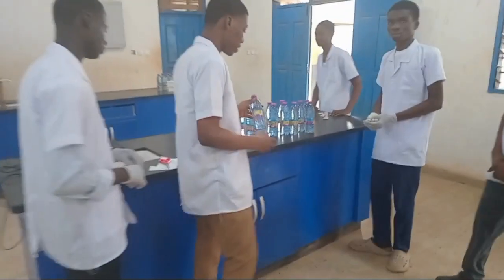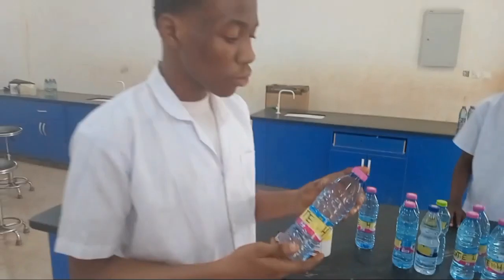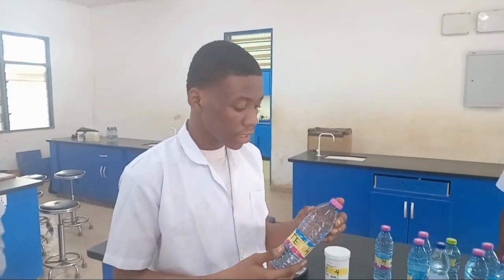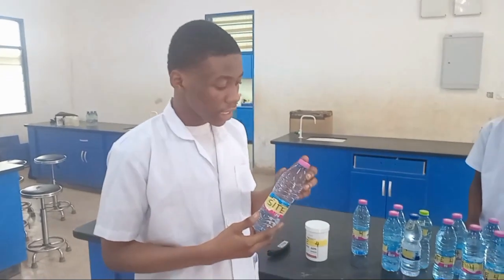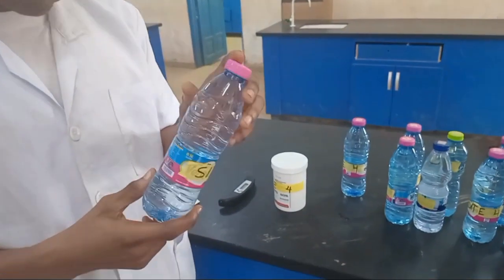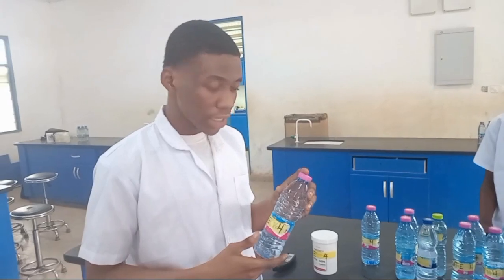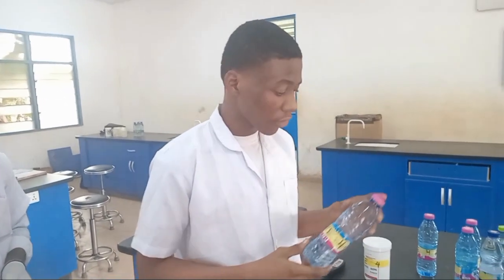So for this sample of water, the transmitted measurement value of turbidity is 0 JTU, which stands for 0 Jackson turbidity unit, which means that there is no haziness or cloudy appearance of the water, which makes it look safe to drink. But in this case, the water might look safe to drink, but it has a pH of 6, which makes it acidic, and it has a dissolved oxygen content of 0 to 4 ppm, which means that it has little dissolved oxygen in it, which makes it unsafe to consume.